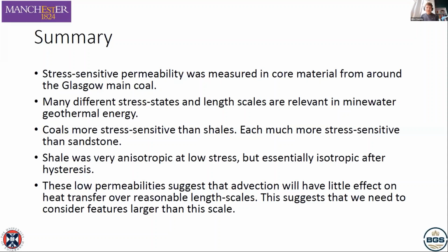The shale was very anisotropic at low stress, but essentially isotropic after hysteresis, so cycling of the pressures. And these low permeabilities suggest that advection will have little effect over heat transfer over reasonable length scales, but that's perhaps more a suggestion that these measures of permeability shouldn't be used at that scale without some kind of modeling to add the impact of larger scale fractures.